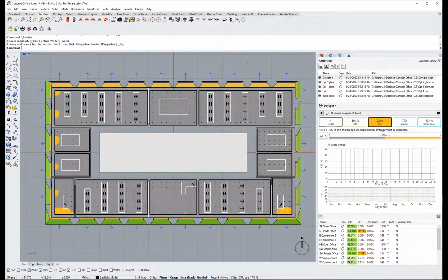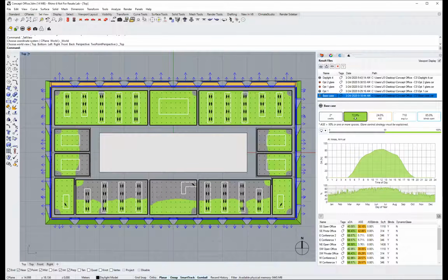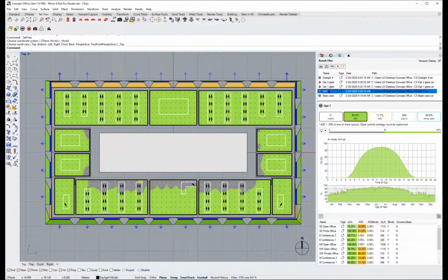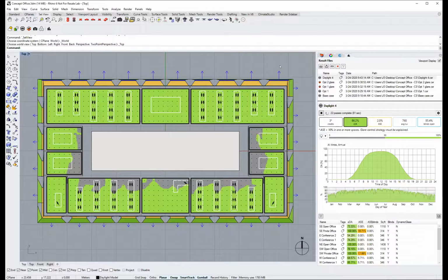So that's dramatically improved. Now let's look at the spatial daylight autonomy. Here we're actually still doing incredibly well. If you recall the base case, we had an sDA of about 73%. Option 1 got us up to about 90%. Option 2, still about the same, so 87%, reasonably close. And so this is still getting us the maximum number of daylight credits. Now it gives me this asterisk just because, as I mentioned, those 2 little office spaces had more than 10%, but that's easily dismissible.